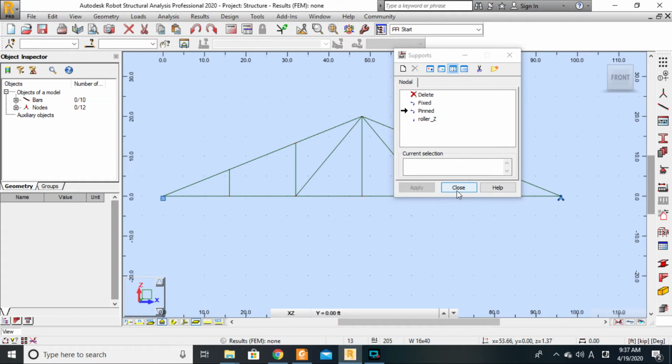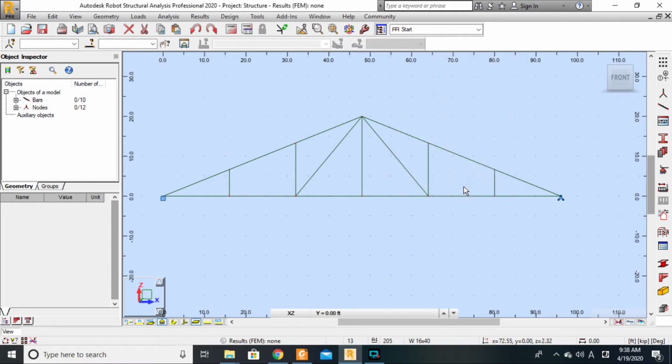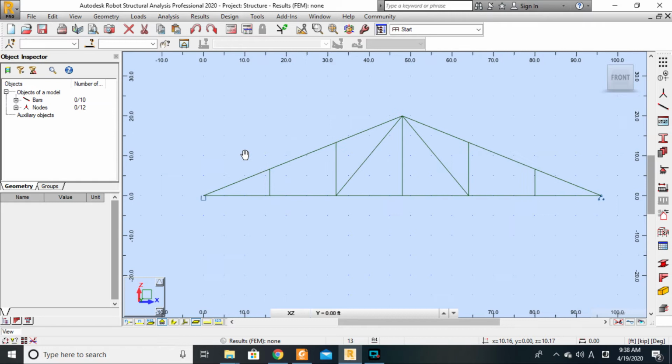When it comes to trusses, right? The pin is modeled as a fixed support because it is assumed that trusses have only 2 degrees of freedom. Okay, only 2 degrees of freedom. So you will not see rotation around there because they are not expected to resist forces via rotation, to resist stuff like bending moment. So it is only forces that they resist. So to say you are blocking all directions in trusses, remember we are in the truss model, right? To say you're blocking all directions in trusses would be similar to saying that you're blocking UX and UY, because those are the only degrees of freedom that a truss has. Okay, translation, no rotation. That's the way it transfers its forces. Good. So that was great.